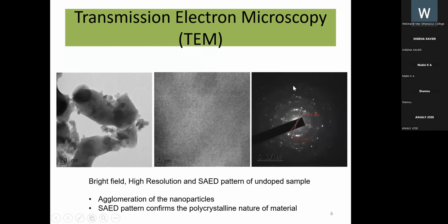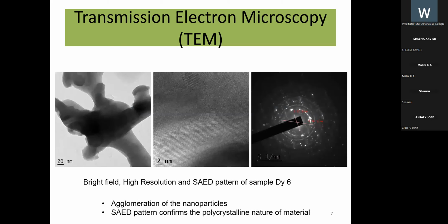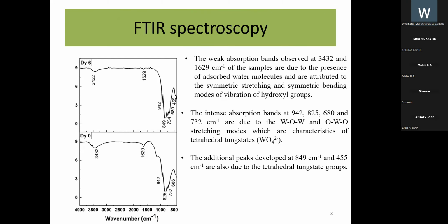This is a transmission electron microscopic image. From the bright field image, it is clear that the particles are agglomerated, and the SAED pattern confirms the polycrystalline nature of the sample. A similar observation is seen for the dysprosium doped samples.